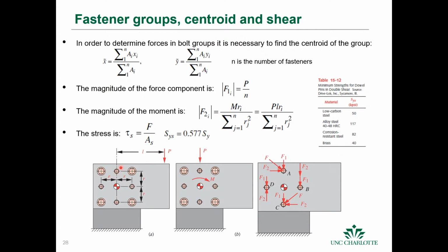Okay, so they all are symmetric. So obviously, the centroid in this case is going to be in the middle. That's often the case for a lot of these textbook problems. But if you have them separated or more spread out for a different bolt pattern, then obviously you have to calculate the centroid. It's not as obvious, but in this simple example, it's obvious that it's in the middle. We do that for the X and the Y.